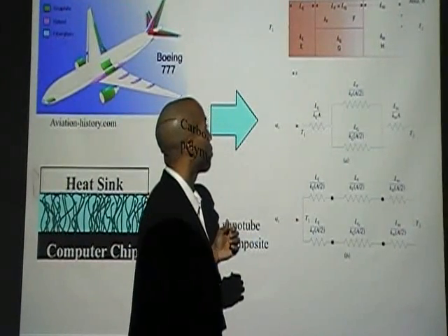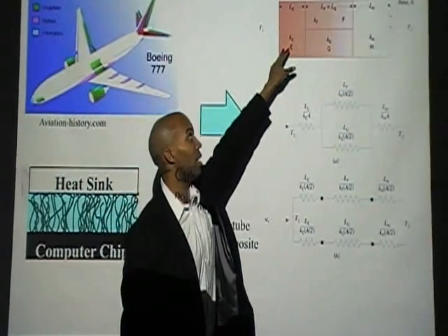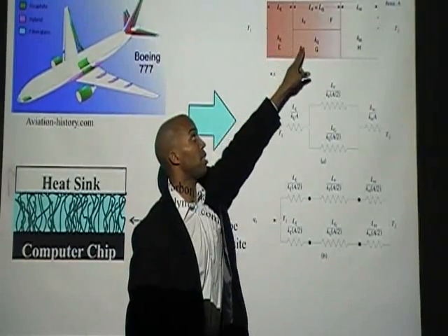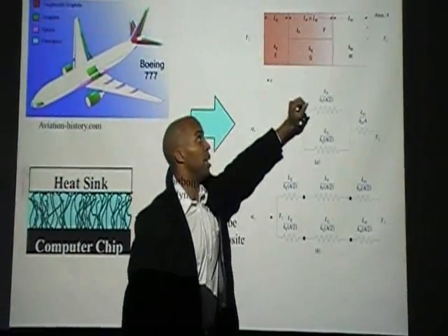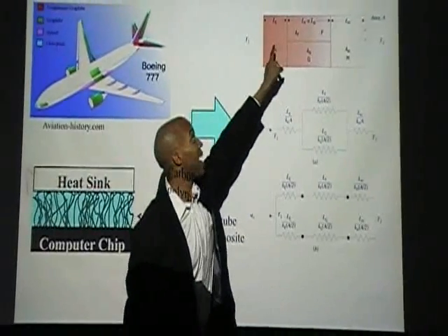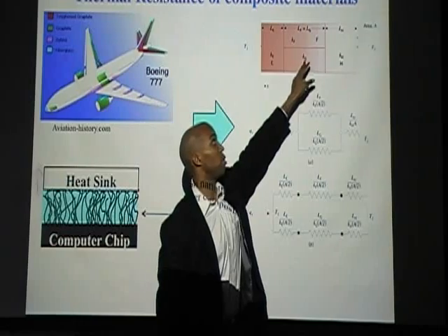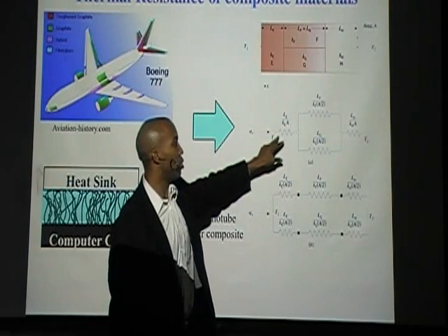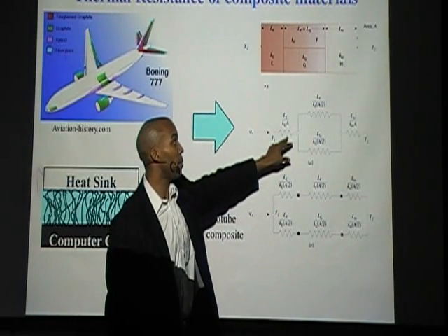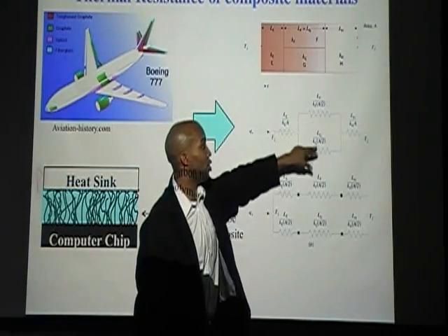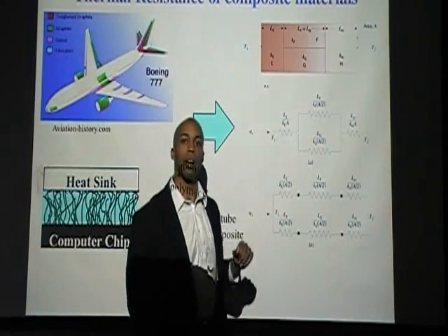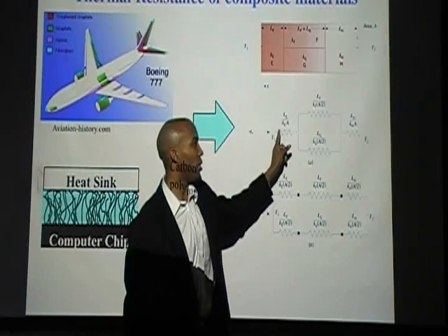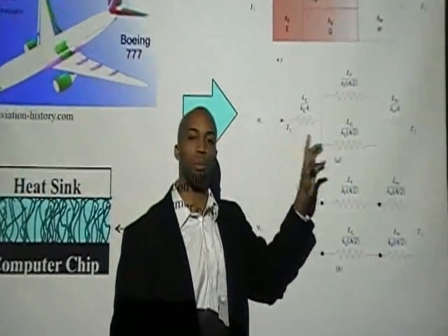In the first approach, we take material E, which has an area in the direction of the heat flow that's twice material G and F. And material H has the same area as material E. So one way to represent this circuit is to have a resistor for material E. Then for material F and G, you have two resistors in parallel. And then these parallel resistors are in series with the other two materials on both of their sides.